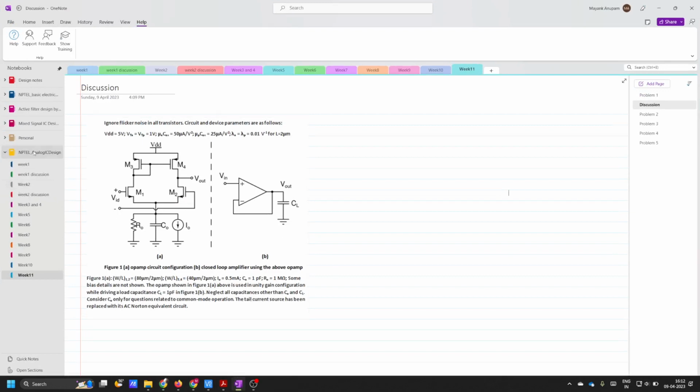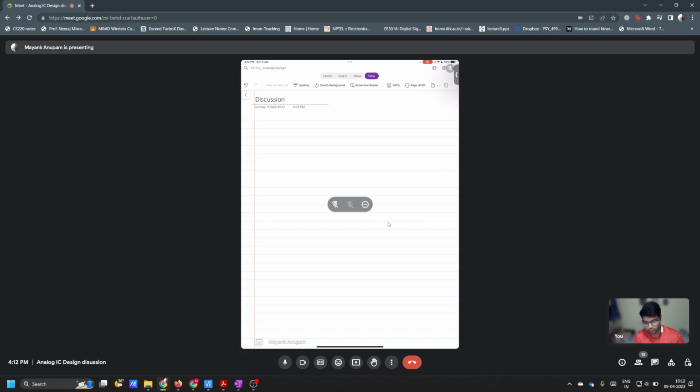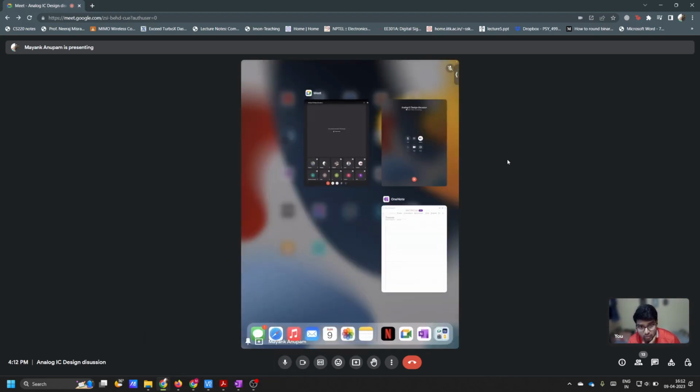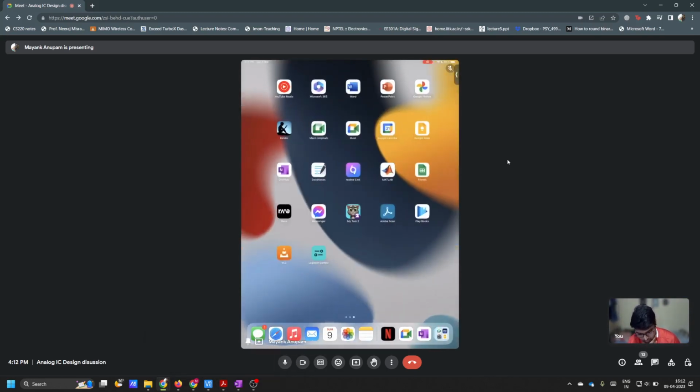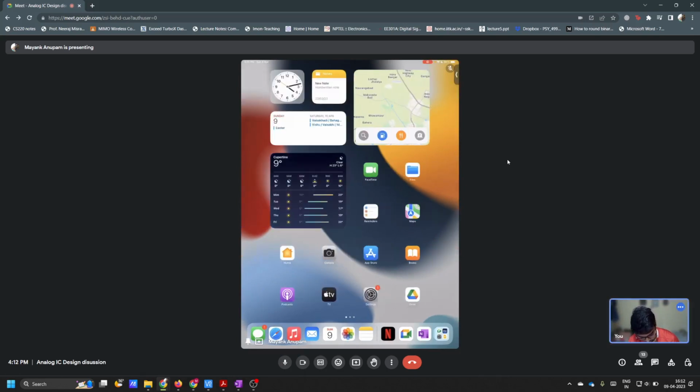Sir, in common mode, if resistor is present, then that voltage cannot be zero, no, sir. No, no, in common mode it cannot be zero in that case. Sir, my question is, that eighth question is there, no, sir? Assume the tail current source requires a DC voltage of 100 millivolts across it to work properly. Determine the minimum input common mode voltage for the op amp.